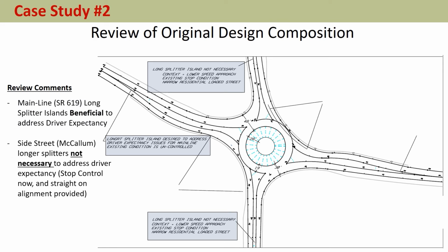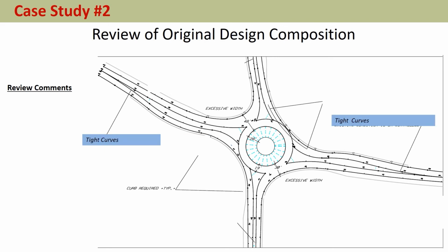In addition, the design has long splitter islands on the main line, which is good. That helps mitigate the application. But they also have long splitter islands on the side street, McCallum, which precludes driveway access and may make more impacts. And those may not be necessary. The driver expectation north-south is a stop sign, and has been for a long time.